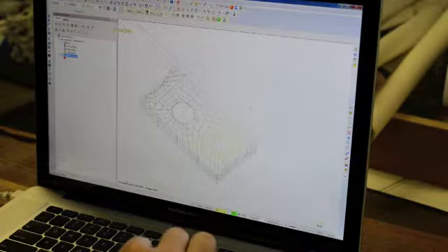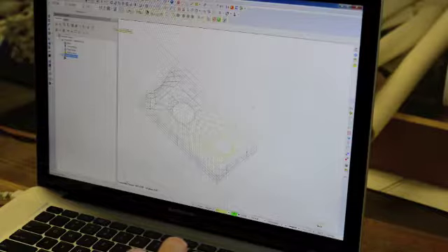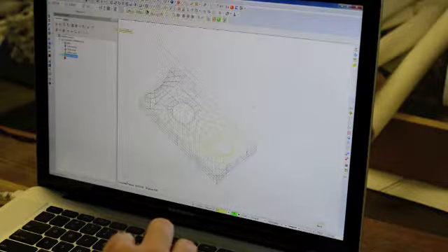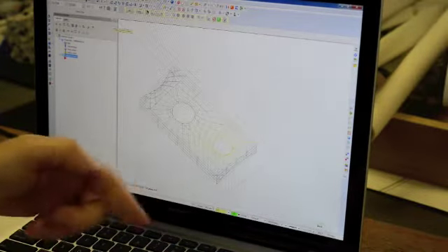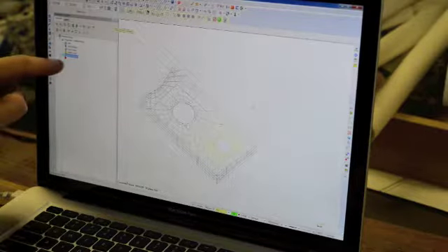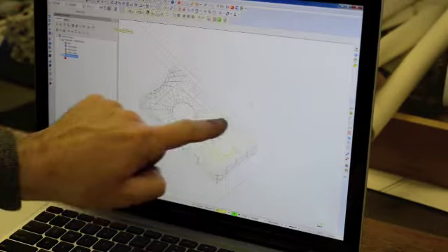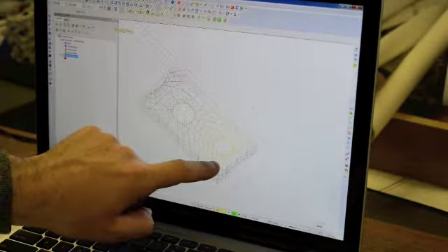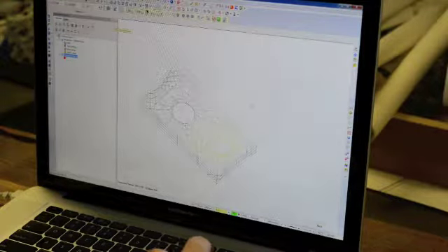So I think when we do this, you have to strategize some type of logical order as to how you want the machine to mill it, because each step, so what we just did right now, if we hit enter and create the toolpath, the mill is going to look over here and it's going to go in order, so it would be like 1, 2, 3. So right now this would be toolpath 1, so that's the first thing it's going to do.